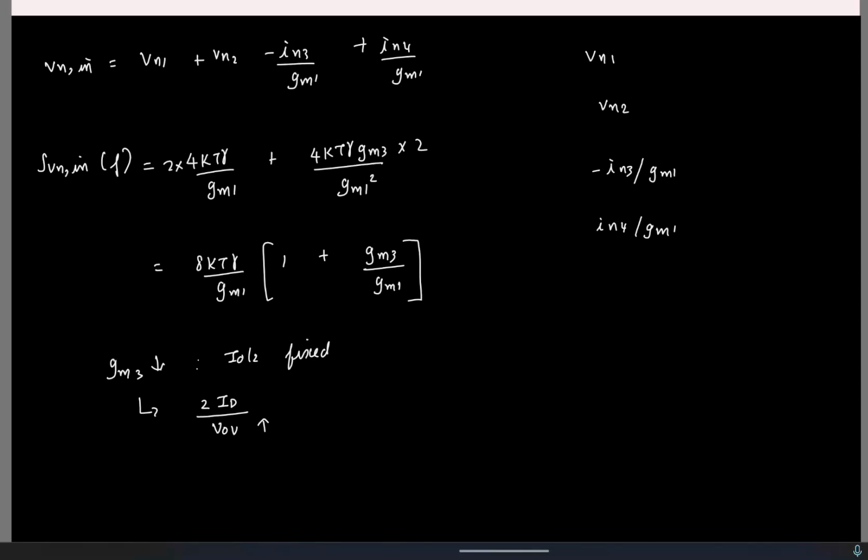Okay, cool. Now in parallel we'll also look at the effect of mismatch. If you recollect, in all our amplifiers we have this differential pair, and in transistors, what are the two things that can be mismatched? One is the threshold voltage and the other is beta. As I mentioned, usually the threshold mismatch is the dominant contribution, so we'll neglect beta.